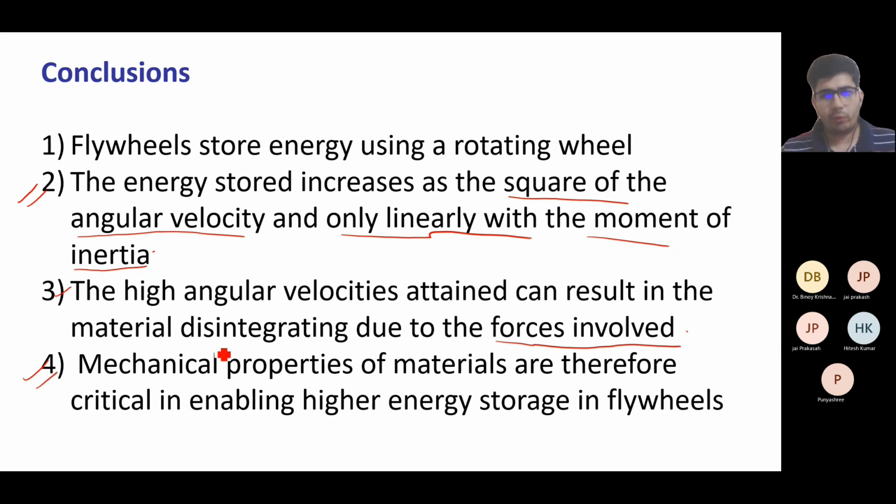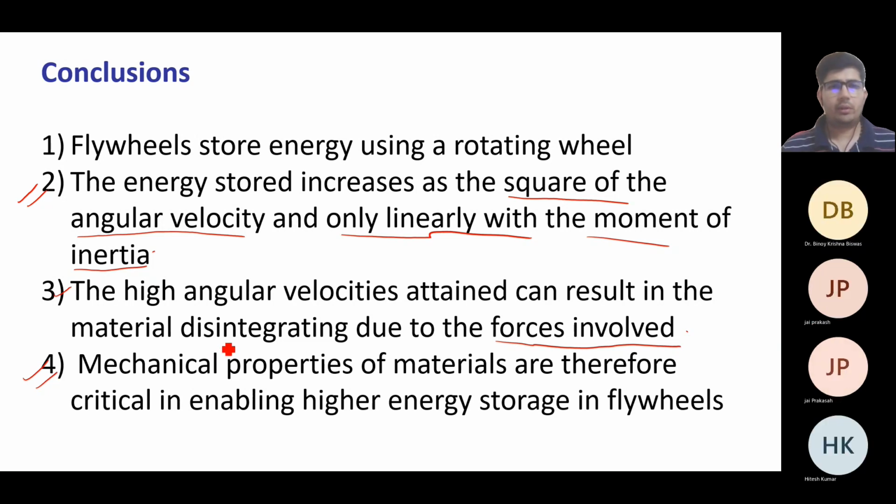So due to the force involved during high angular velocities, stress will be there. So the mechanical properties become important. Whenever you want to select a flywheel for a particular system, you have to identify the maximum angular velocity that the system can attain.